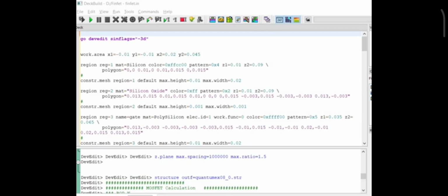After the region statement, mesh creation is to be defined. You can build a mesh by base mesh, the geometry and impurities, and mesh constraints, and create a mesh using the mesh parameter available options. Mesh parameter: base mesh height and width may be used to create more symmetrical meshes for some devices.